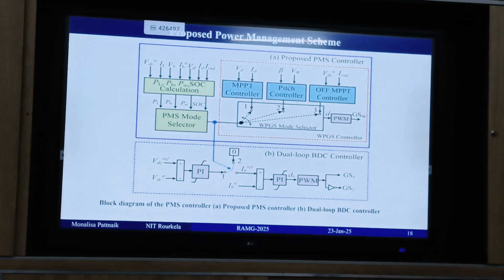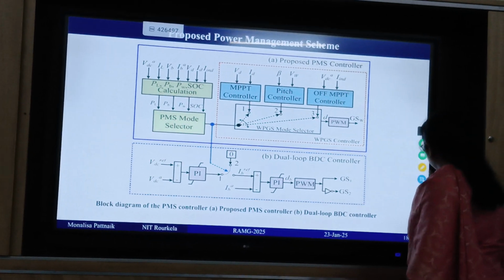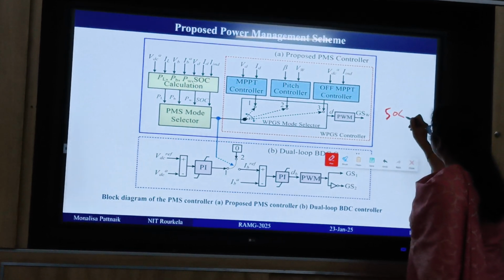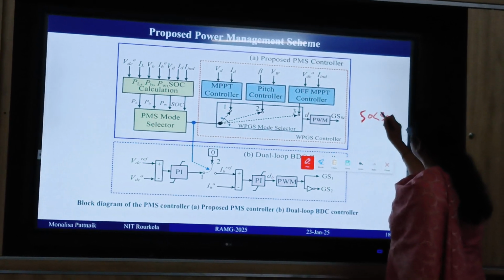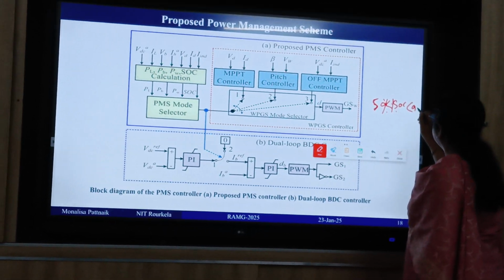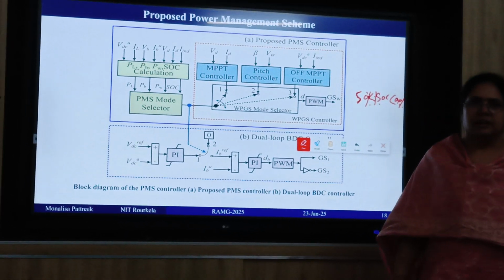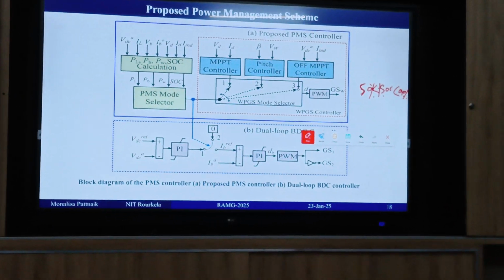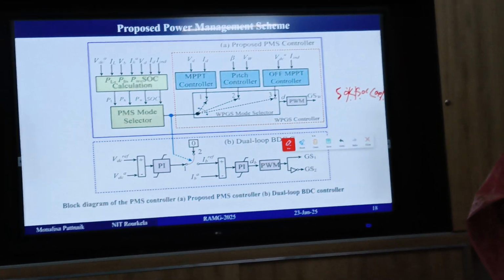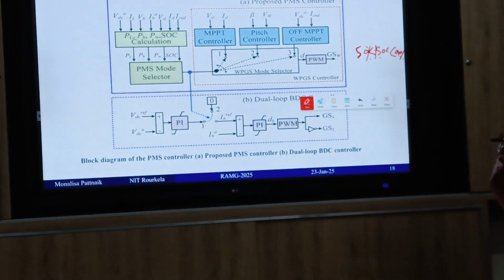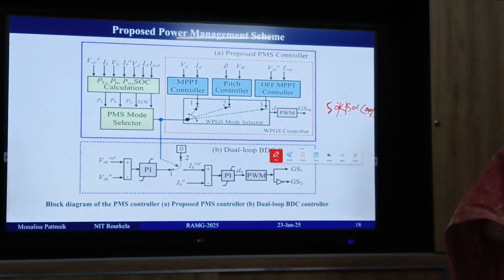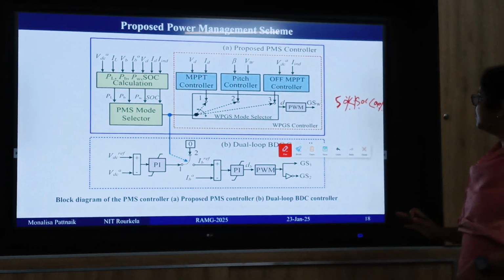Okay, that is, SOC is between 50% to 90%. First we have taken that range, and I am calling it the normal operating scenario. Okay, so that means my battery is in a safe condition and I can do my operation of generating the power from wind, and if the load power is less, I can store it in the battery. Those basic operations we have tested.